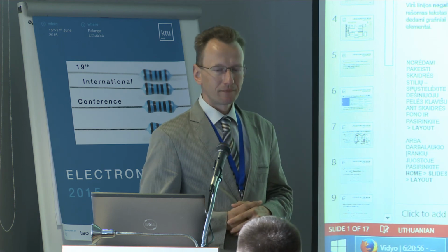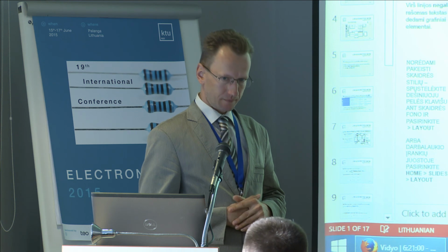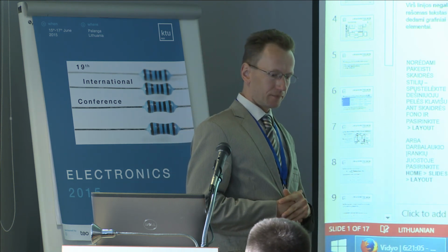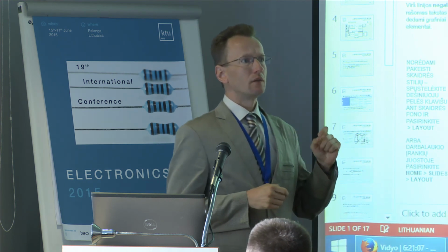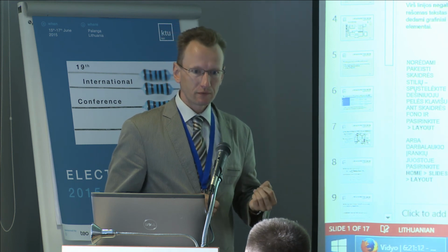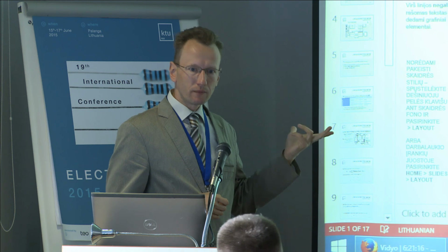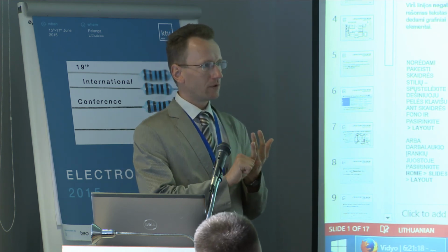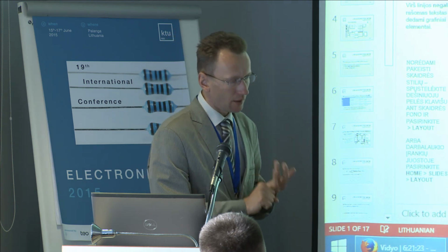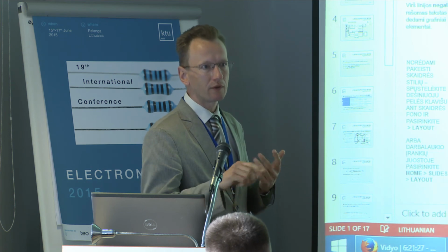What was the way of estimation of uncertainty? Did you use the analog to digital converter of the microcontroller in your calculations? The calculation was done by calculating. We have a formula or a measurement model. We take parameters, we change them like 8 bits, 10 bit, 12 bit, and calculate these uncertainties with these settings.